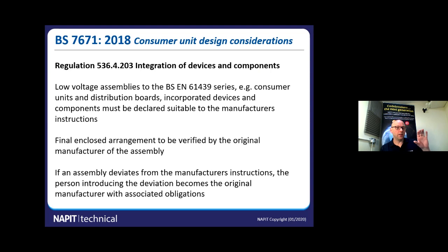If you put a different device in there, you take on the obligations, and if anything happens with that consumer unit, even if it's nothing to do with your alteration, you're going to be responsible. The manufacturer will not warrant their board because you've made the deviation. So let's be very clear, we do not recommend this moving forward.